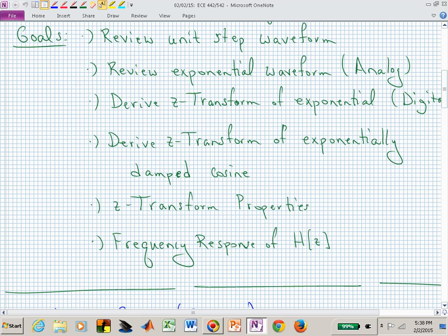Now, where does the imaginary axis in the S-plane map to in the Z-plane? What's another way of thinking about that imaginary axis? As another hint, does that give you some kind of boundary, the imaginary axis? If you're on the left of that imaginary axis, what do you know about your signals? They're decaying, aren't they? If you're to the right, in the right half plane of that imaginary axis, they're expanding or growing. That imaginary axis is our boundary for stability.